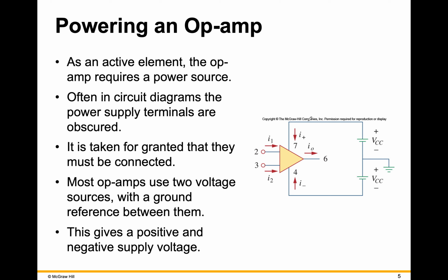Actually, it was a filter, and what they would do is sometimes they would not realize that the VCC had to have a negative and a positive. You couldn't have one of the ends connected to the ground. So that's kind of a common mistake in the lab. There are some op amps that do allow that because they have an internal system that will split the voltage. But the common op amps that you buy cheaply, you usually have to hook them up like this.